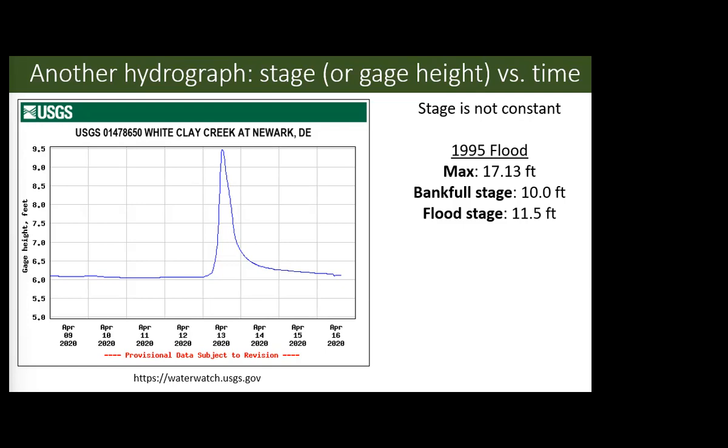So for this specific one, on the y-axis, we're measuring gauge height. For this specific location, this is the max that it's ever seen. The bank full stage is 10, the flood stage is 11.5. At this specific point, are we at a flood stage? Yes or no? Yes. Are we sure?